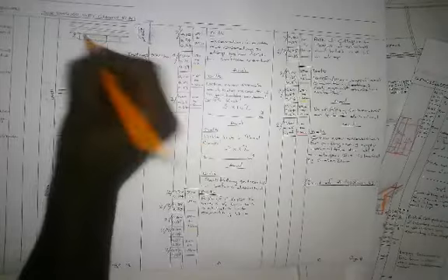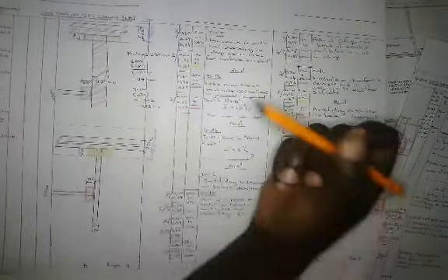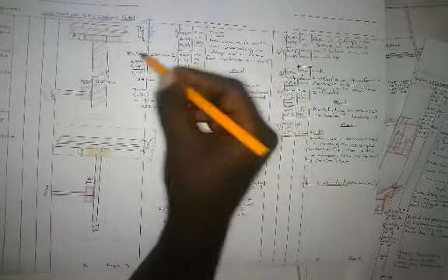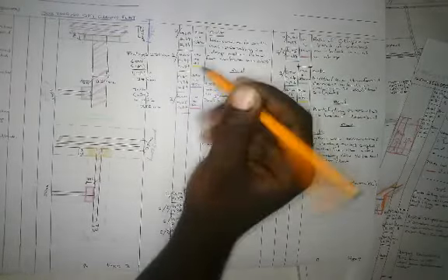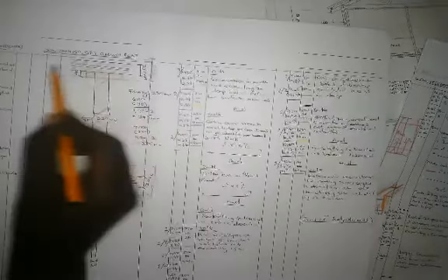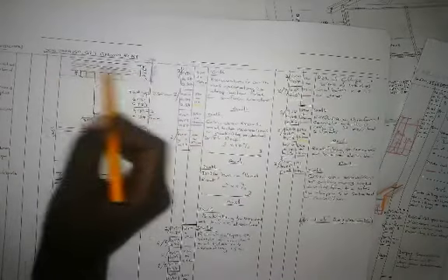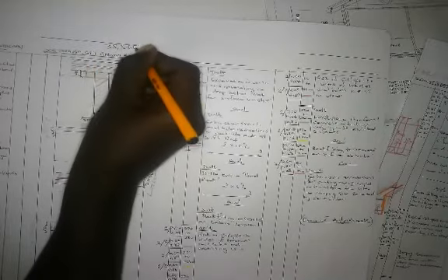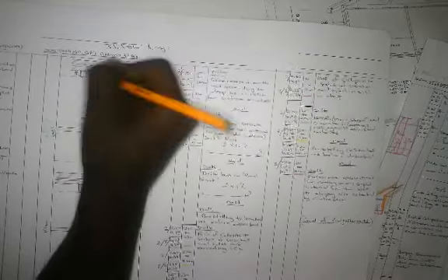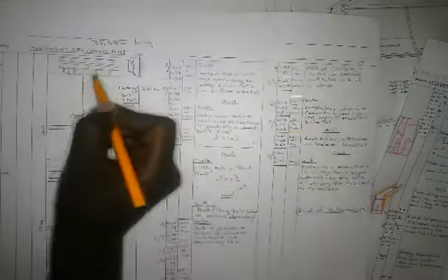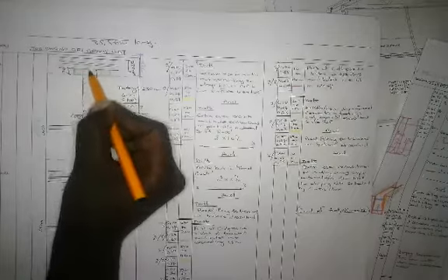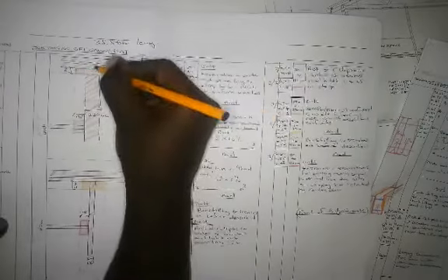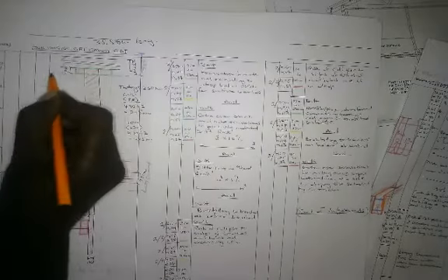Here's the important part that I thought you were interested in: the adjustments. The adjustments are done because we cannot over measure, guys. We cannot over measure because excavations also cost money. It costs money to excavate and do something. So let's take for instance this wall. This is a 270 cavity wall, the one that is represented by 35.56 meters long.